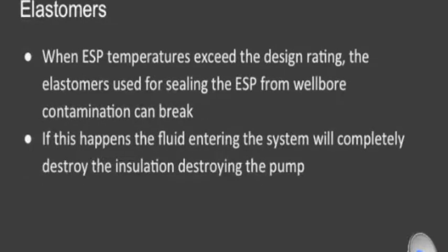The main cause of motors overheating is elastomer failure. When ESP temperatures exceed the design rating, the elastomers used for sealing the ESP from the wellbore contamination can break and melt. If this happens, the fluid entering the system will completely destroy the insulation, destroying the pump.